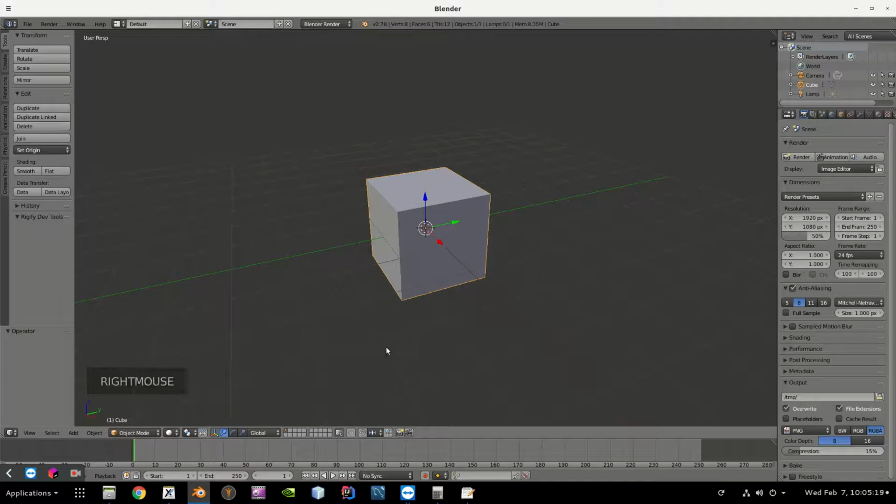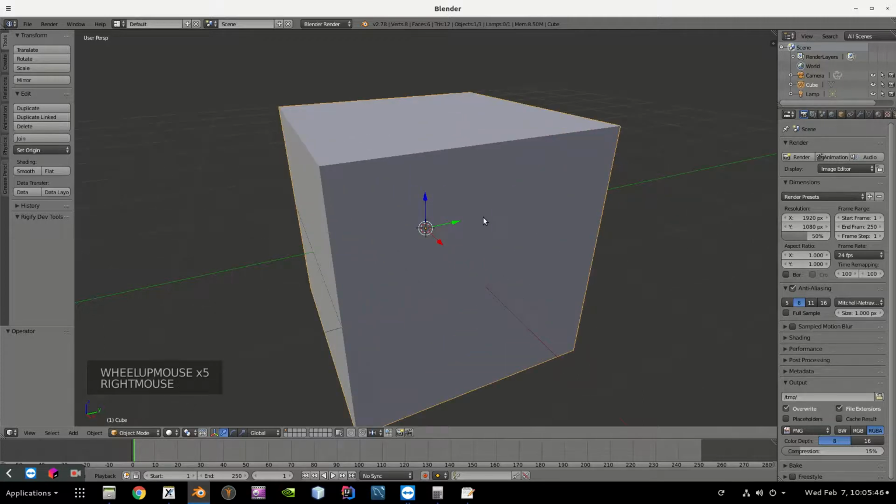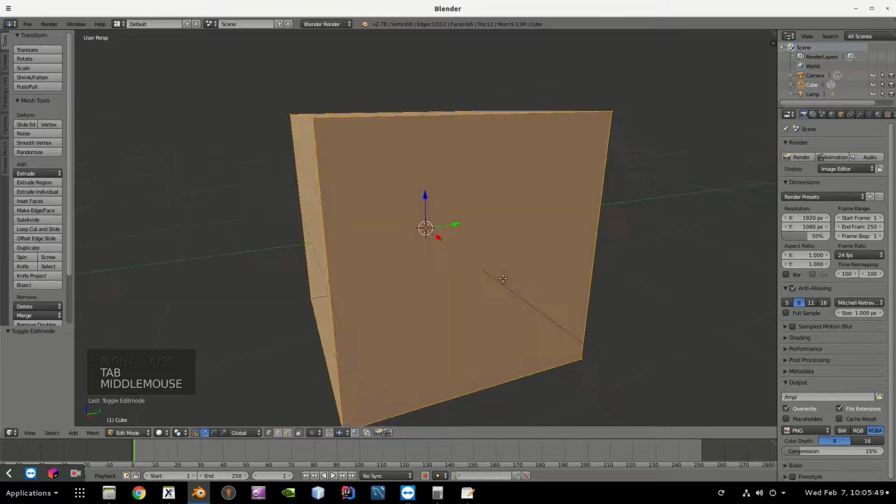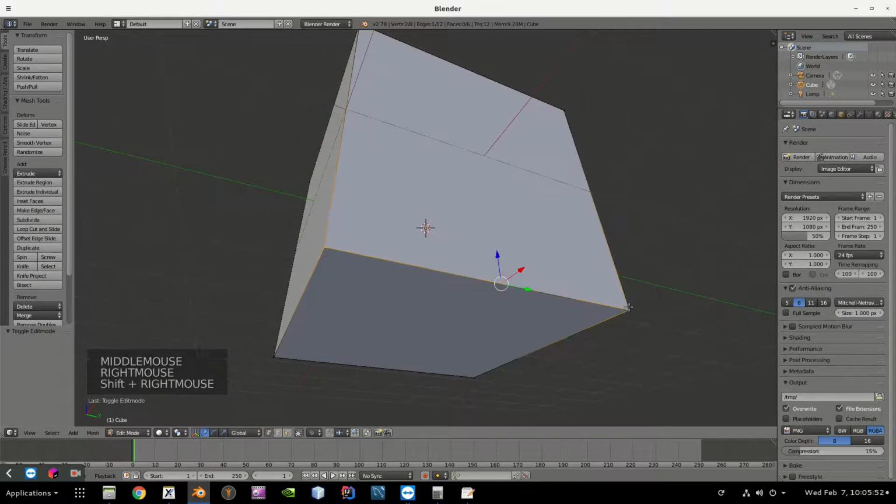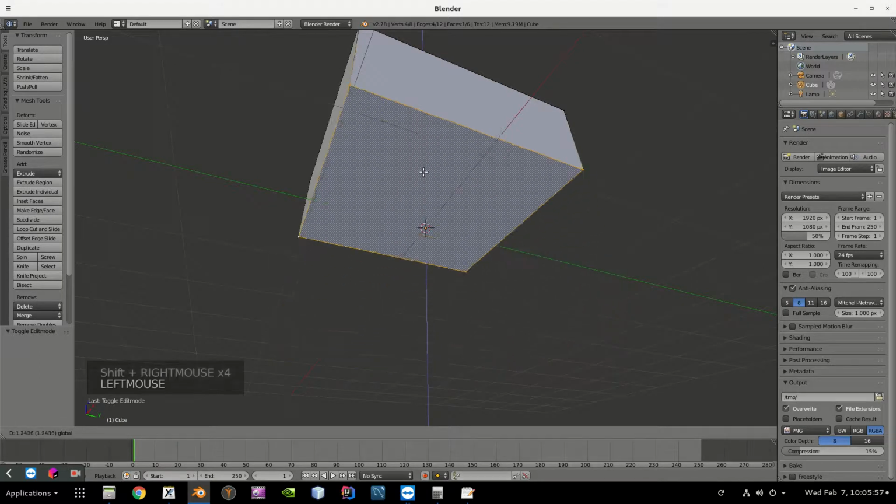See, previously what we did is we selected this cube and edited the geometry, like we scaled it in the z-axis to make it flat, right? If I wanted to build this top surface over here, I'd have to squeeze it down in the z-axis. That's one way to go. However, it's going to be much easier if I get direct control on the geometry, and we can do so just by going into the edit mode. And now we got this surface over here, which we can select all four corners and then move it up just like that.